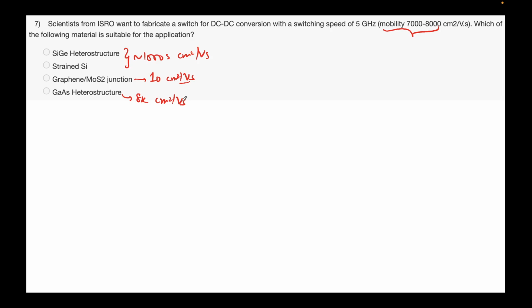That's the whole idea of this. Okay, so for this application, gallium arsenide does suit our need because it has the higher mobility that we require. For certain applications, gallium arsenide is not suitable. For certain applications, there is another compound semiconductor called gallium oxide, Ga2O3.